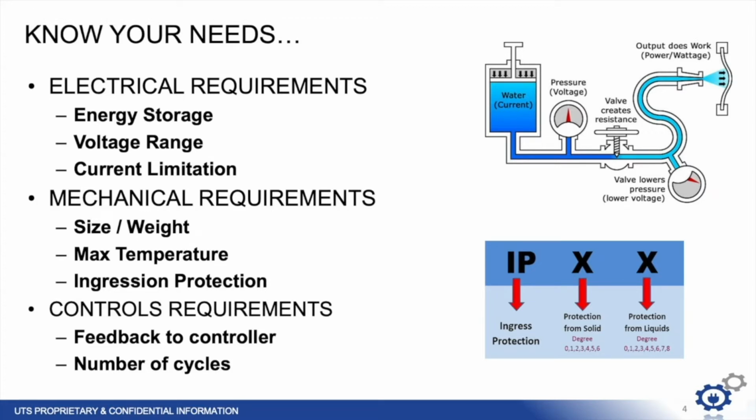As I said earlier, the best applications for ultracapacitors tend to, among other things, need high power or high currents, or repeat a cyclical charge and discharge profile. If we think about some example applications, maybe an ultracapacitor module acting as load leveling on battery storage, or perhaps a bank of modules act as bulk storage for a high power gantry that repeatedly accelerates and decelerates a large load. But in nearly all cases, the application requires more than one cell, and so those cells need to be configured in series and parallel strings to achieve the electrical requirements.